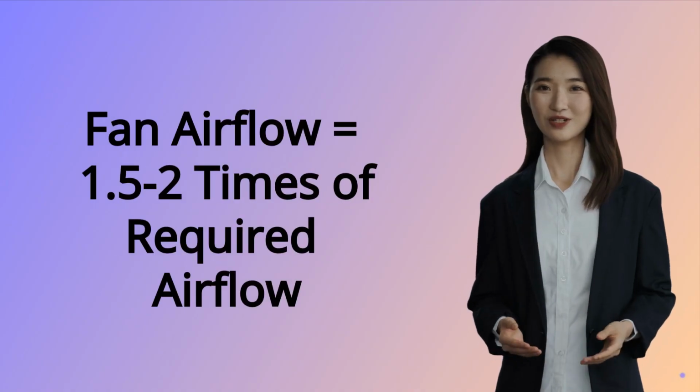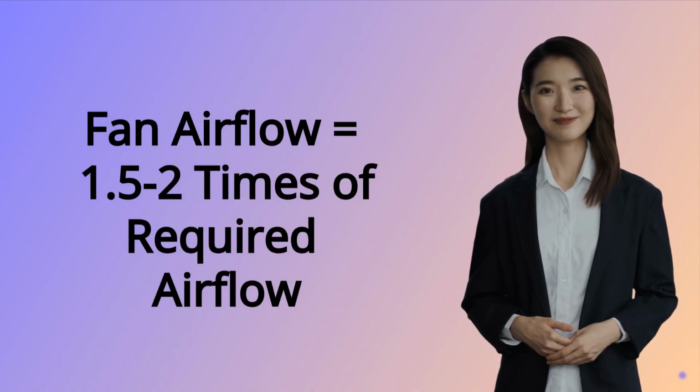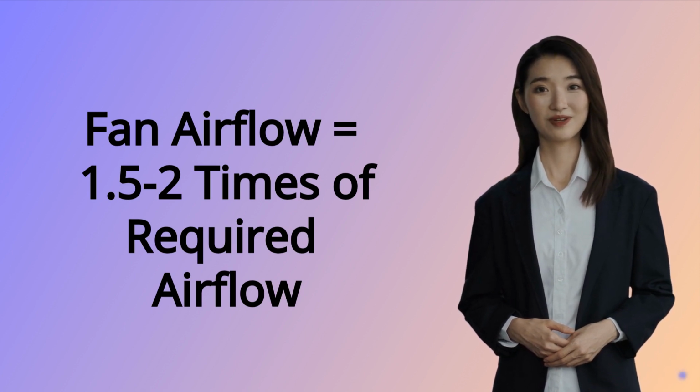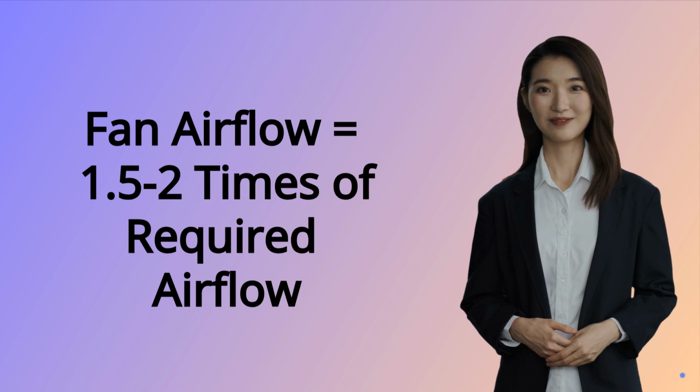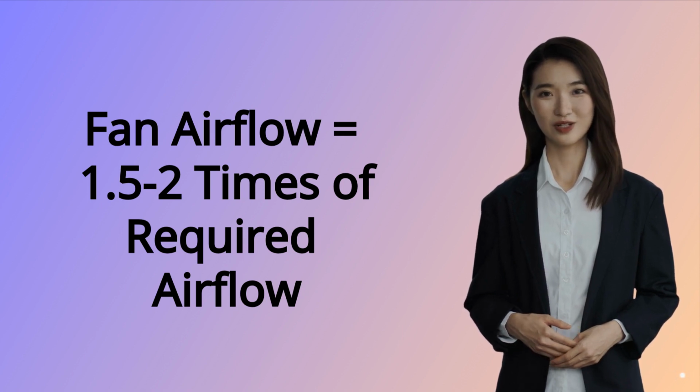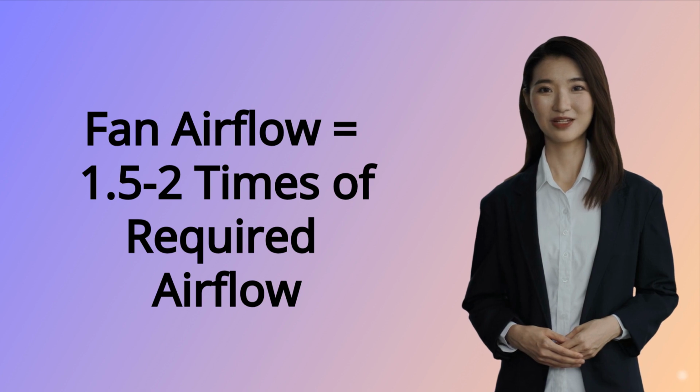Usually, we can't measure system impedance very accurately. So, it's a good idea to pick a cooling fan that can handle 1.5 to 2 times more airflow than you need. When choosing a fan, just looking at the maximum airflow listed in the specs isn't enough. Airflow isn't the only factor in measuring cooling effectiveness. It's also important to choose the right cooling fan based on the system's impedance.